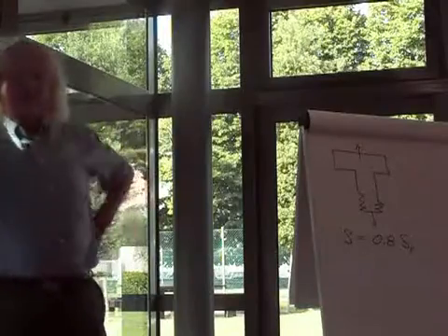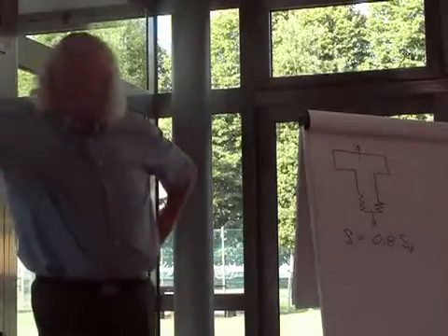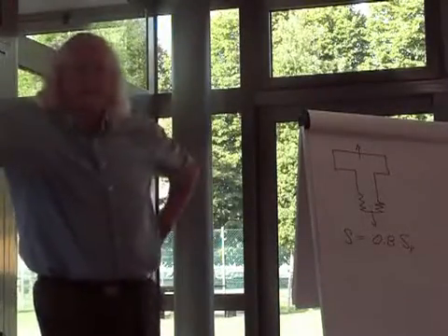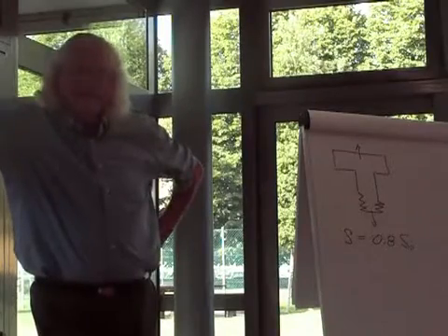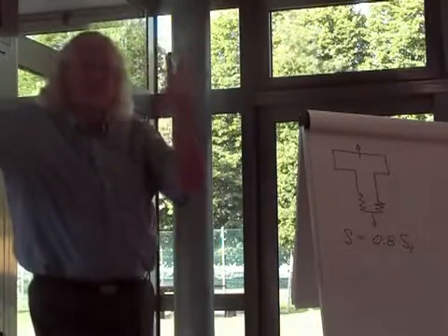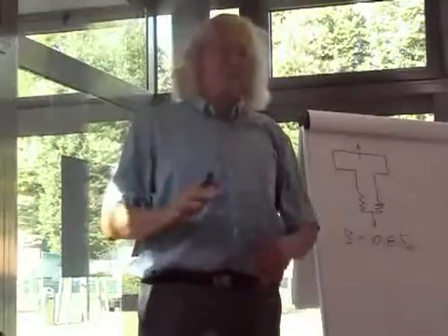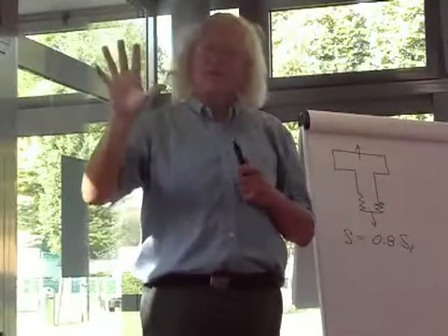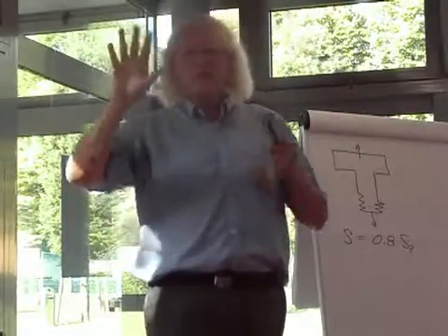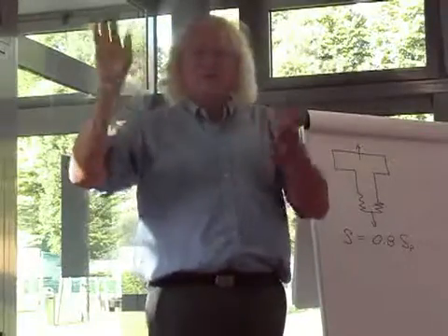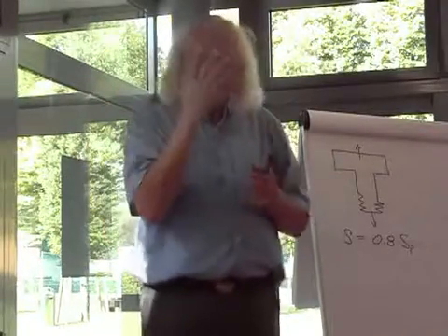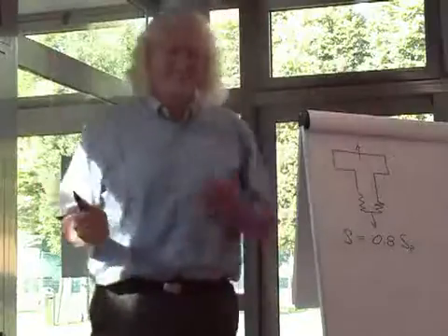How about the stress concentration factor for threads on a bolt? Approximately 3. Good answer. 3 is a universal answer, by the way. If you don't know the stress concentration factor and you guess 3 to start with, nobody can argue. They can say, oh, I think maybe it's 2 or something like that. But you know, 3 is the good starting point, always.